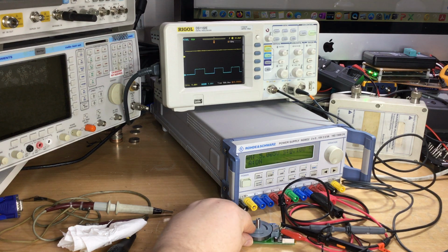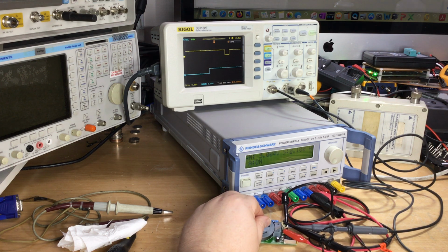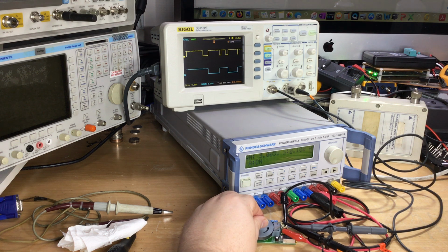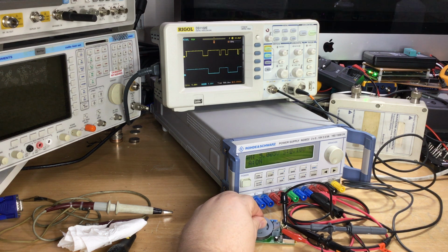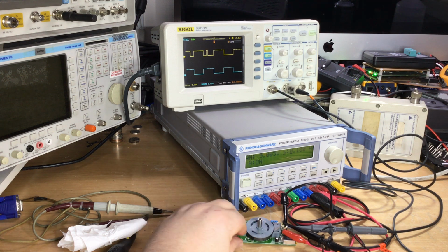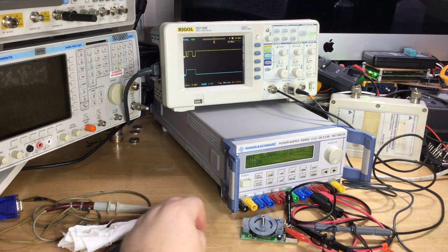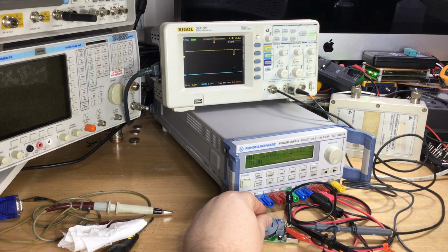Now if I push the Hall effect sensor back up to the disc, again you can start to see in a moment when it sorts itself out the pulse train at the bottom compared to the top. The top's gone erratic completely. It doesn't matter what you do with that Hall effect sensor, whether you push it closer or pull it away, that pulse train never gets any better. As a matter of fact, I'm just going to try and edge it out just a little bit away from the disc, a couple of millimeters, which I've just done there, and we'll just try again and see whether that improves things.